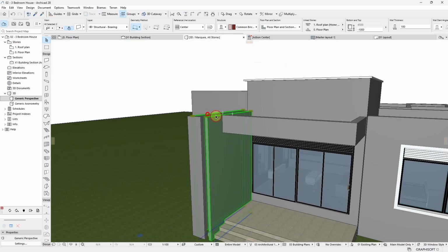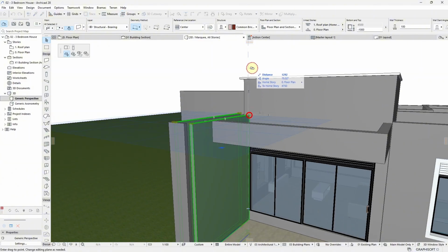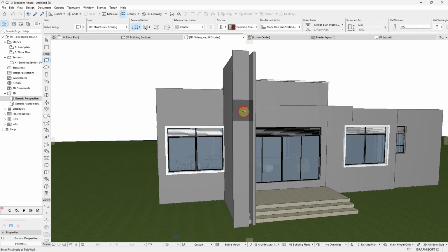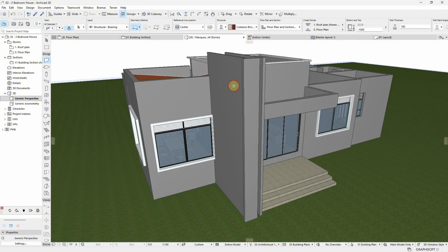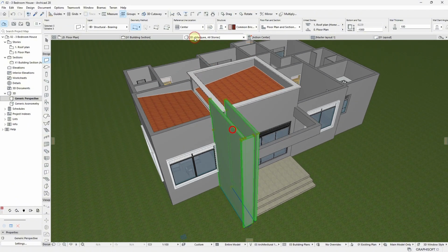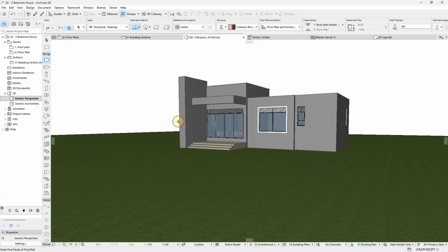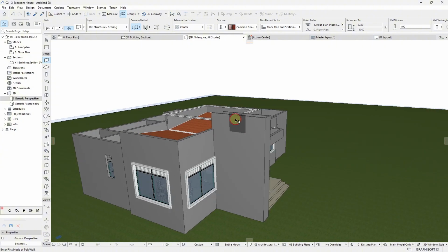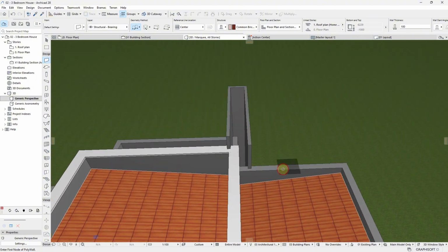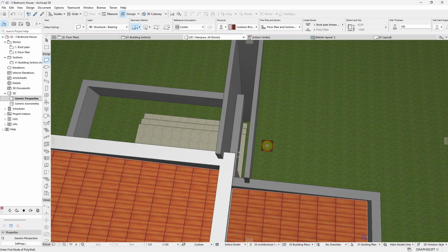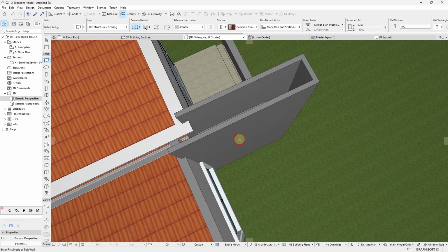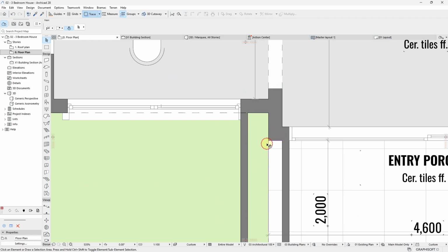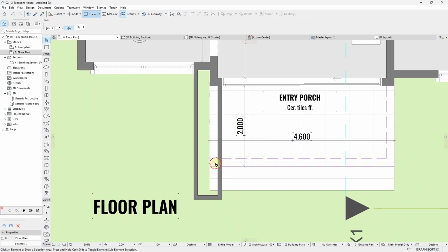So what I did next was to pull this wall all the way up to somewhere here, and this wall gives me a design of this sort. After having this kind of design, you will notice that our gutter is going to be placed directly here, and it will all drain outside. So now this becomes a duct, a bigger duct, where our roof will drain from.